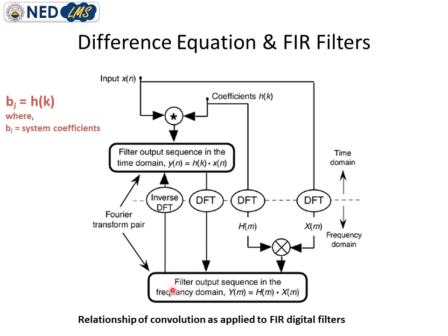Now if we again take the inverse of this frequency domain output, we will transform back into the time domain, because we know that when we take the DFT, we convert the samples from time domain to frequency domain, and if we take the inverse DFT or inverse FFT of this frequency domain version, then we will transform back to the time domain.